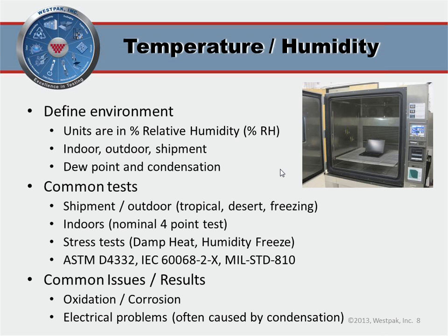So, with our testing, define the environment. Usually, shipment is the most severe for an indoor operating product. Two common test conditions there are tropical, which is usually 40 degrees C, 90% relative humidity, and desert, which is 60 degrees C and either 15 or 30% relative humidity. These would be good non-operating conditions for our laptop. For indoors, there's generally no need to test.